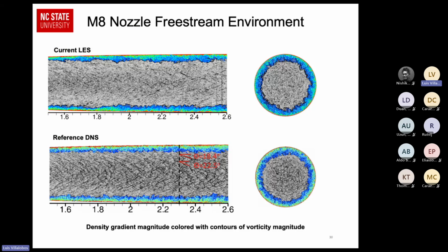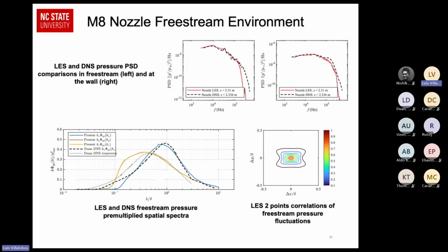And as I showed in these plots, something is not matching in terms of the wavelength energy. Prahlad may add to this, but the key thing with all of these recycling or inflow methods is they all work when you have a clean flat plate geometry and enough developing length. But say if you had an adverse pressure gradient occurring very quickly, then depending on what development length you have, your profiles start not quite responding to what you need, and you may not have enough region to play with.